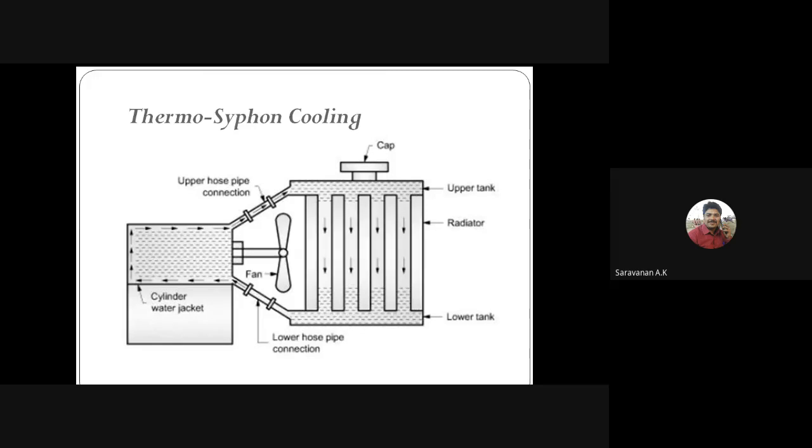So in this thermosyphon cooling, the system is designed so that the water may be circulated naturally because of the density differences, depending upon the temperature. If the temperature is hot, the hot water will have low density. At the same time, the cold water will have high density.